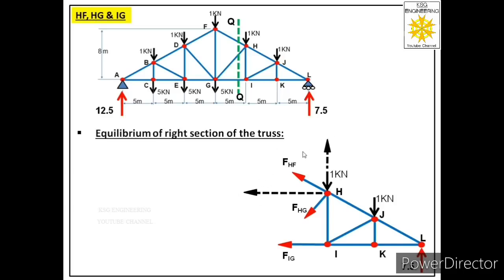So for that, first of all we have to see the angle of this force with any of these 2 components. So let us locate the angle of this force with the horizontal component. Let us call that angle as theta. Now let us find this theta first. You can see this theta is similar to this angle because this is the same line, and to that line we have drawn 2 horizontal lines. It means these angles will be same, that is corresponding angles.